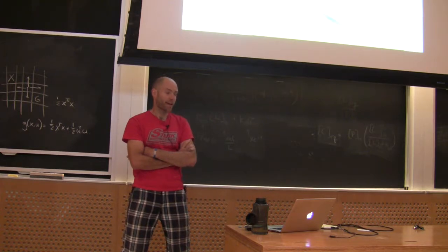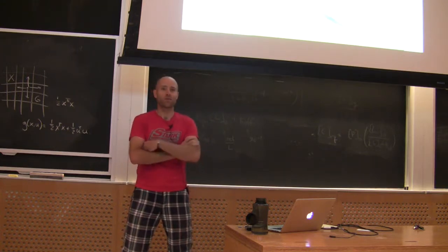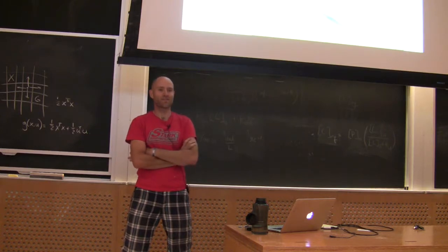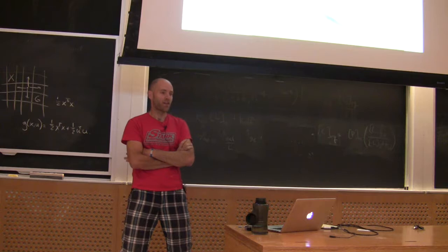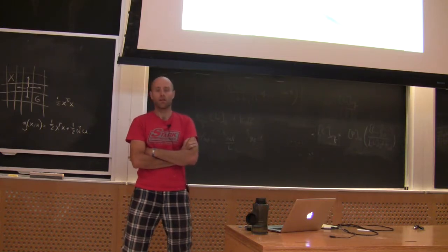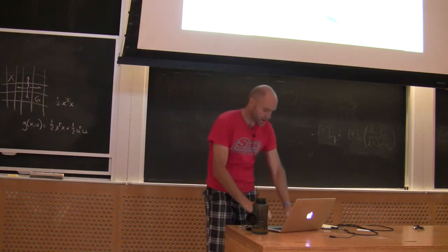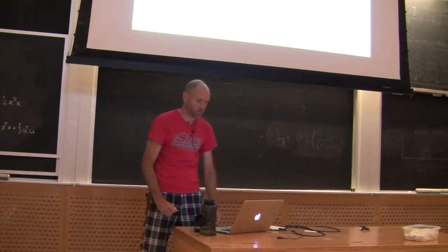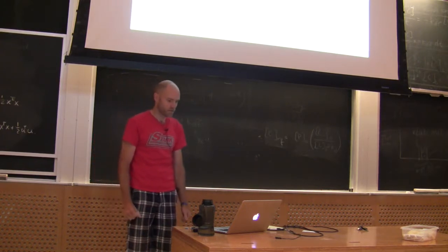But I can't do dynamic programming on Atlas. Making that graph discretization for something that has 68 dimensions, or 72, depending on which way we write it, is just not going to work. So there are limitations to it, but it's surprisingly powerful, and we have to remember how well it works. That's the min time solution for the pendulum.